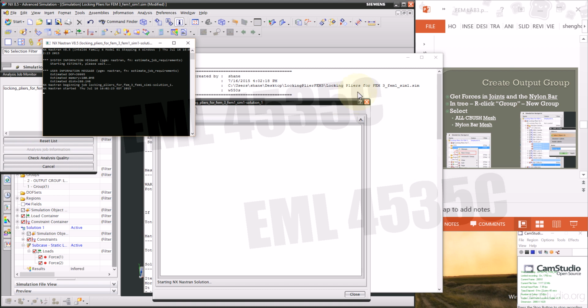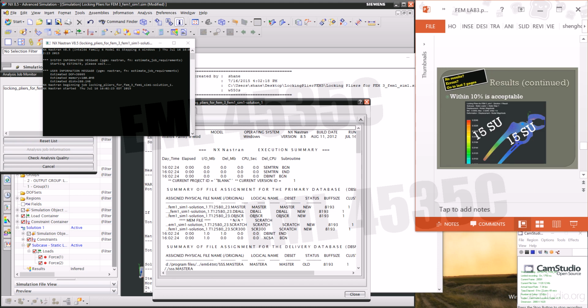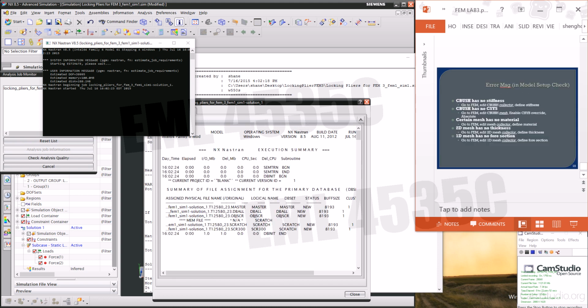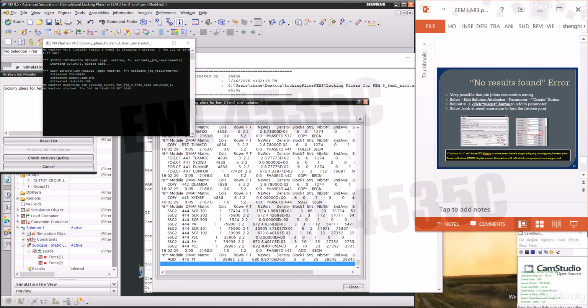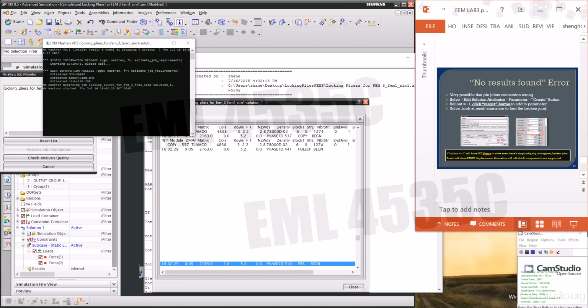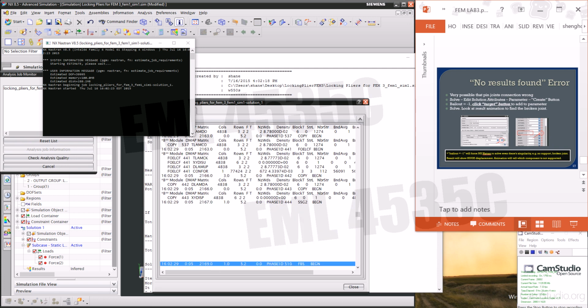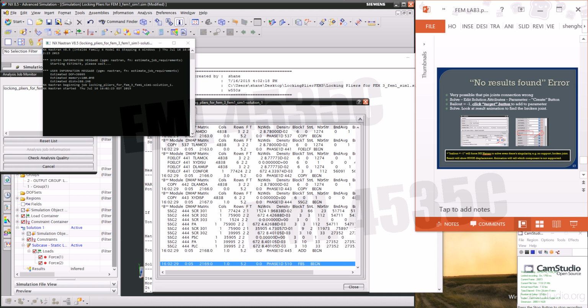And if your solve didn't go through, you should look at the last 2 pages for the troubleshooting. Okay, first the troubleshooting is no results. That means you don't have enough support most of the time. So you can turn on a parameter to force NX to run, and run the animation in results.